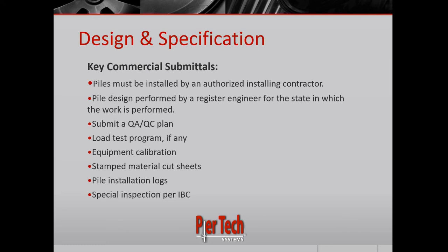Typically, you won't see a special inspection requirement for residential work, decks, foundation repair. Certain municipalities will require that, so make sure you check on that before you start a project, so it doesn't hold up your permitting or slow down your project there.